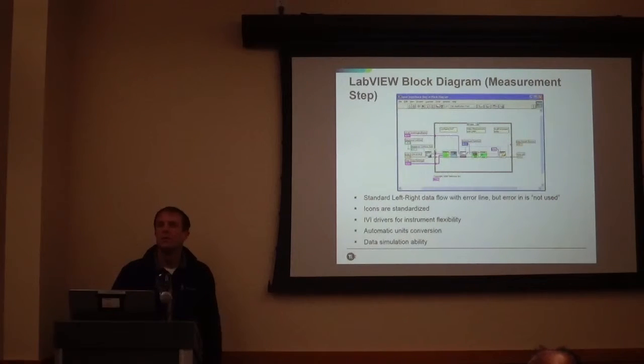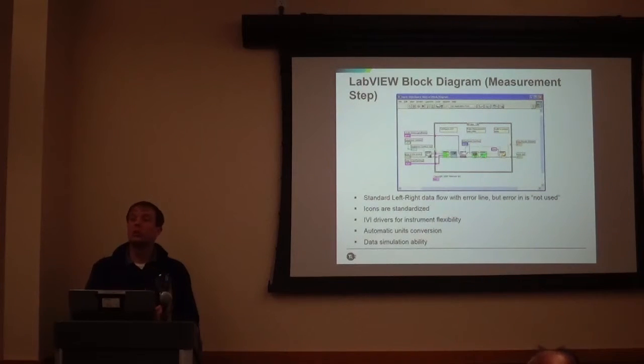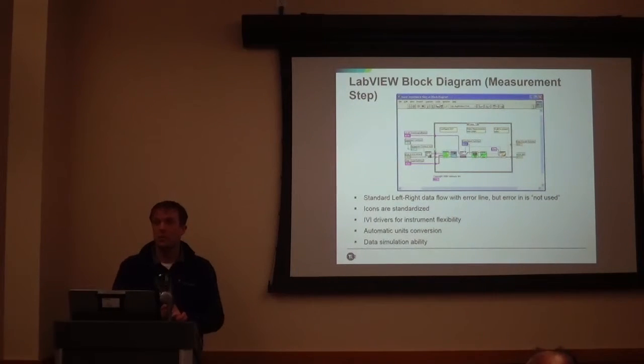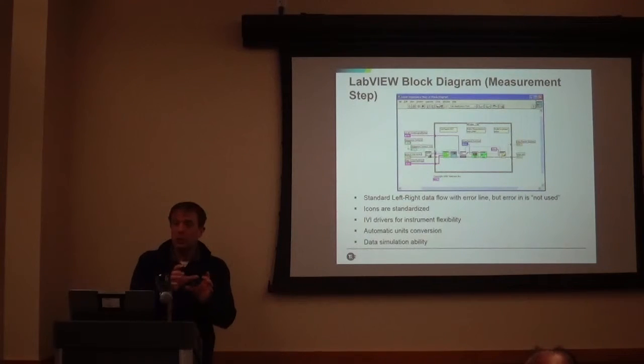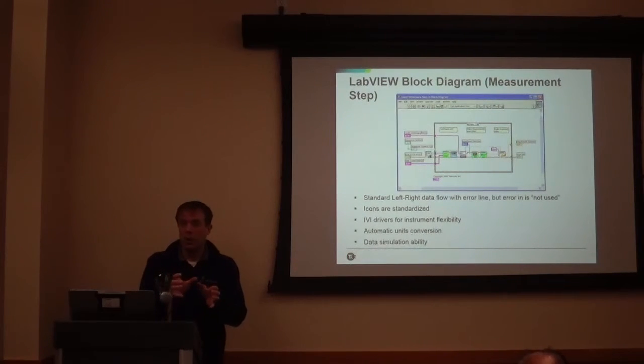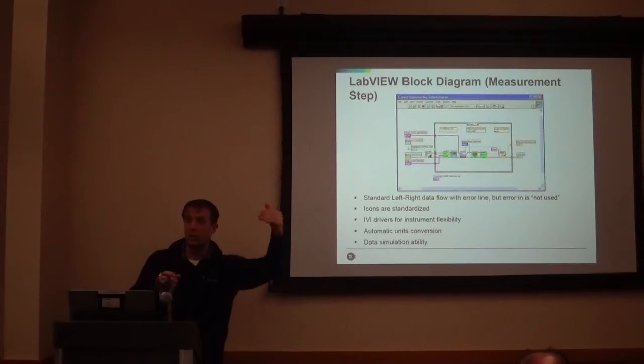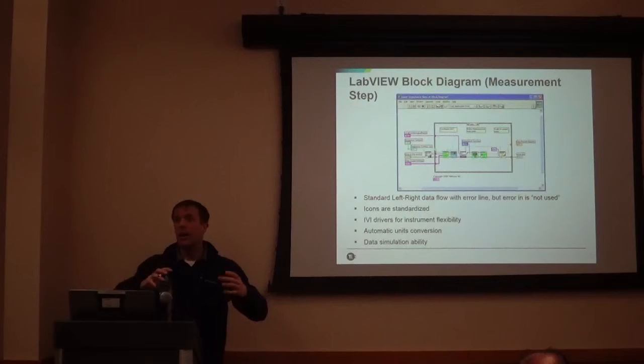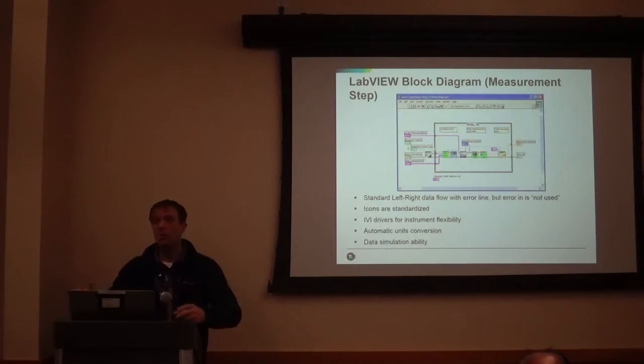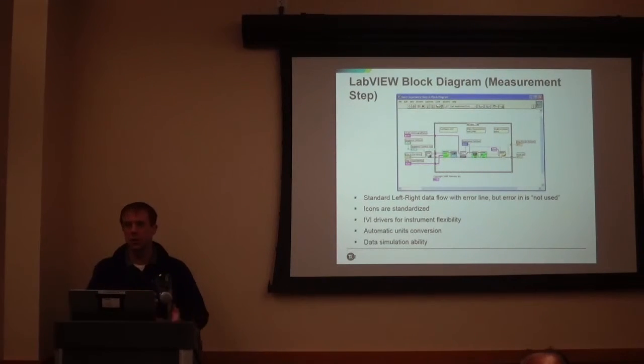If you are writing code in C++ or LabVIEW, I can do everything in LabVIEW, so why do I need TestStand? Because TestStand is your sequencer and your test executive. If you need to write a bunch of test modules, and then take all that data and generate reports and log it to a reporting database, those things are standardized. That's where TestStand comes in.